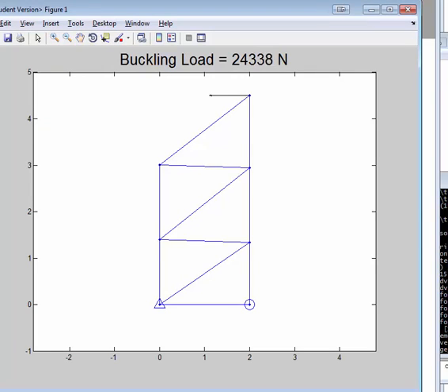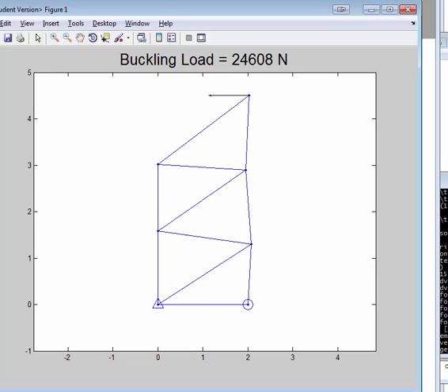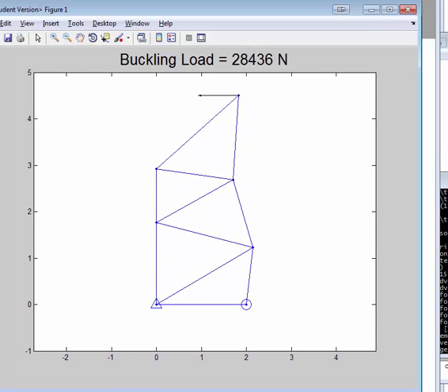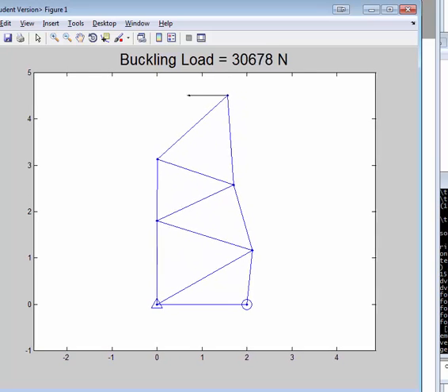You can see here that we're gradually increasing the actual load that this particular structure can support. We can achieve that simply by nudging up and down the various joints in the structure. But we can also go further and move all the joints except for the tip and the base ones. We can't change the height. And we can see already that by shrinking some of the beams more dramatically, we can construct a much, much stronger design than we could originally.